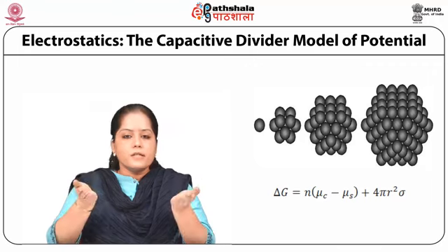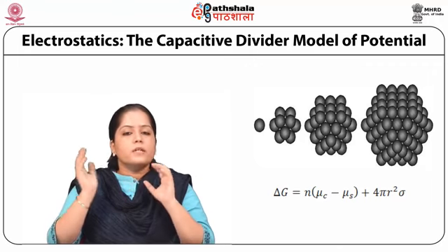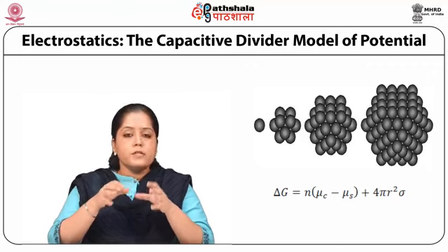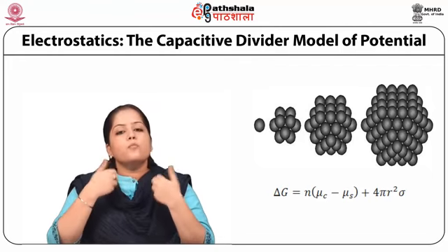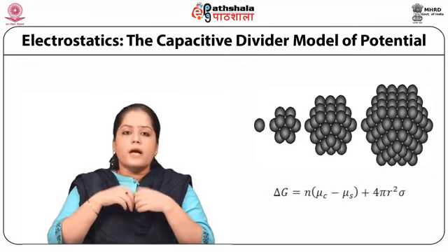However, we are interested in the opposite case, with the chemical potential of atoms in the solution being more than that of the bound atoms. So the first term becomes negative, resulting in the free energy being a maximum for a certain critical radius RC at which a nucleation barrier is imposed.